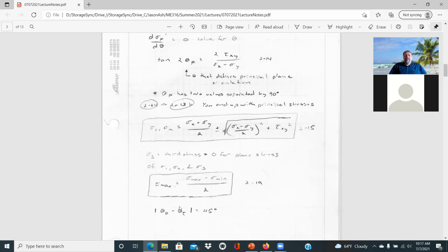But that relates then back to the Mohr circle. If you were to draw your Mohr circle related to that, I do have an example coming up, just reminding you on the Mohr circle. But in some occasions, say for example, if you have two positive principal stresses, sigma 1, sigma 2, say 10 and 15 megapascals if you're using SI unit systems, you'd have a third principal stress of 0 megapascals.